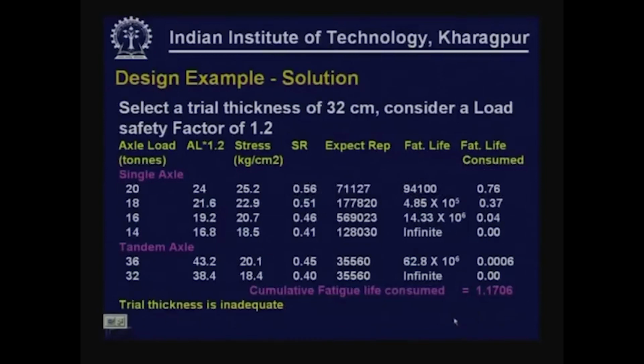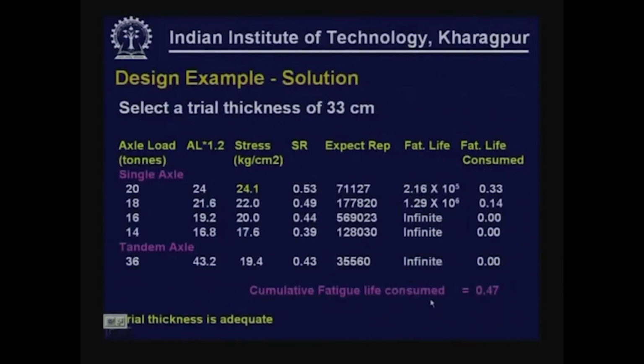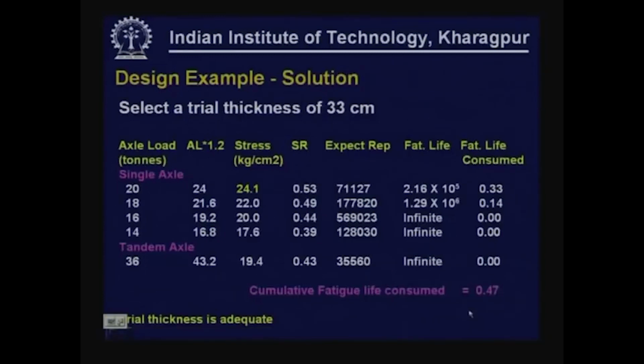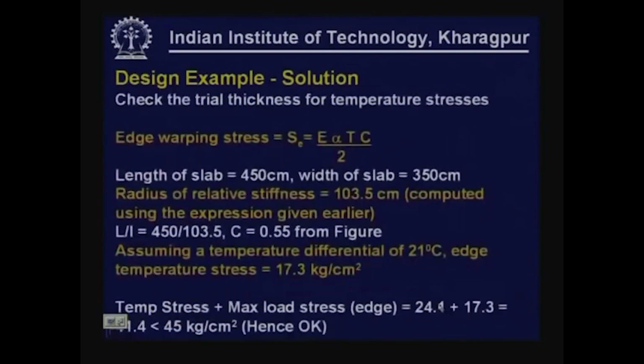So, the exercise is repeated with another trial thickness of 33. We can see that the cumulative fatigue life consumed here is 0.47, which is acceptable. So, the slab is now safe from fatigue considerations.